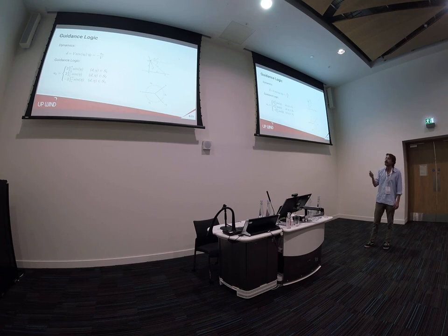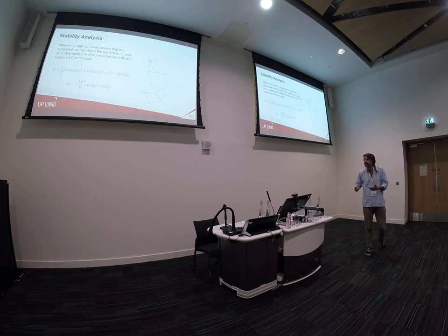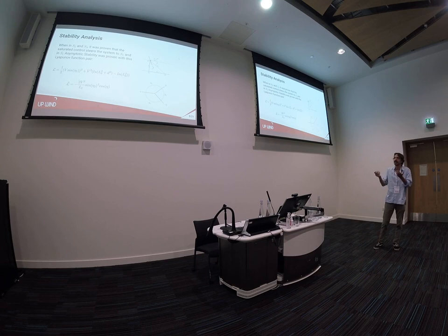On this guidance logic, we did a stability analysis. We proved that in the saturated regions, the saturated acceleration, so our guidance logic, will steer the kite to the unsaturated region, S1. And in this unsaturated region, we proved using Lyapunov analysis that this guidance logic is stable. This isn't really a control session, so I can talk a little bit about what a Lyapunov analysis is.